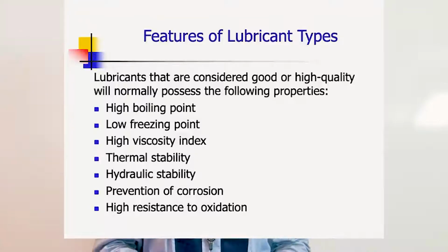And the viscosity index must be very, very high for a good lubricant. What it means is that if you drop a drop of that lubricant here, it should be able to hold its own and not flow away immediately. If the viscosity index is low, what it means is that as you are dropping that lubricant, it just vanishes into thin air, leaving the surfaces dry, and then they can easily make contact, and the problem is not solved. Then a lubricant must have what we call thermal stability.